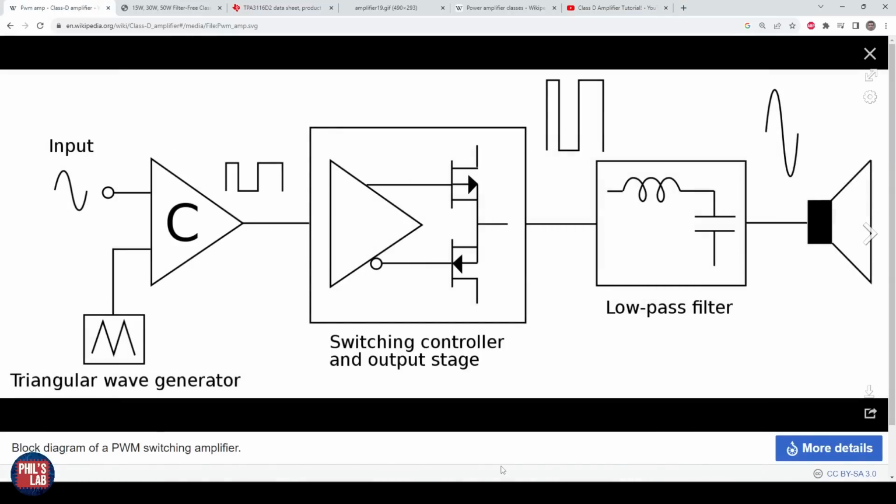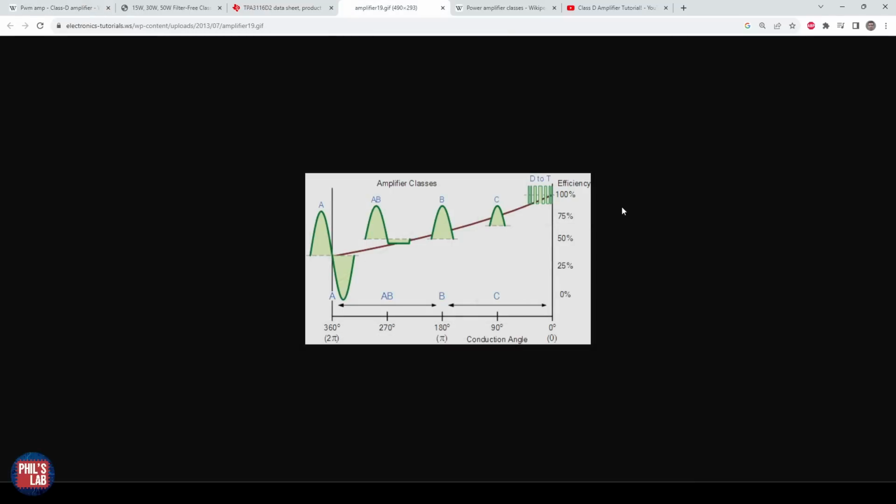With these types of amplifiers, we are predominantly looking at audio applications. We might go from a low-level, line-level input signal, which might come from a CD player or your computer audio output, and we want to drive, for example, speakers of considerable size on the right-hand side. Somehow we have to convert our input signal, which is low level, low energy, into a fairly high power, high energy signal that can drive these speakers. Amplifiers for audio exist in many different wattages, with power ratings anywhere from a couple hundred milliwatts to several kilowatts. Class D amplifiers are especially useful because they provide very high efficiency, theoretically up to 100%, but of course in practice it'll be lower than 100% efficiency.